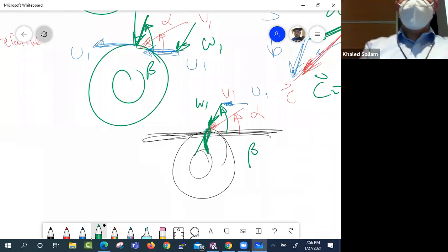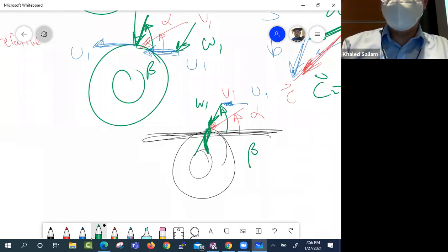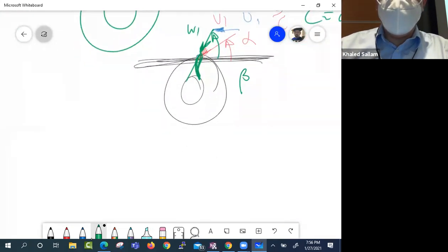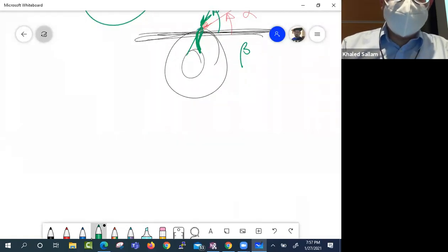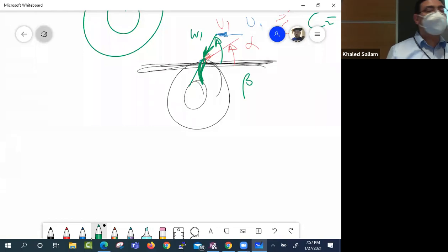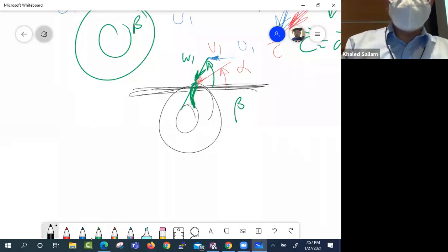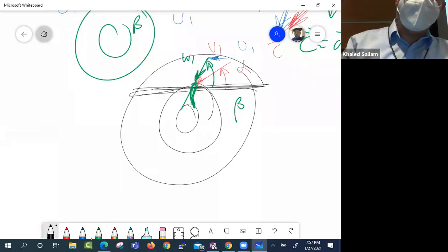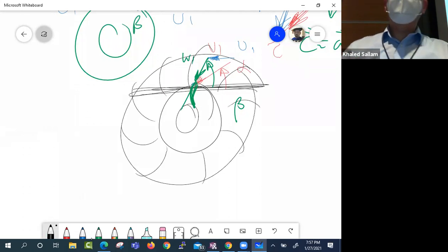Okay? So we know the angles' names, and we know the relation between W and V. The last thing I want to say is that it's all about unspinning the fluid. The stators will spin the fluid for us, and the rotor will unspin it and extract the tangential momentum from it.